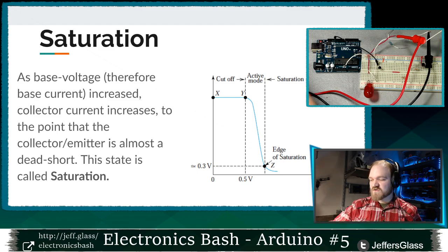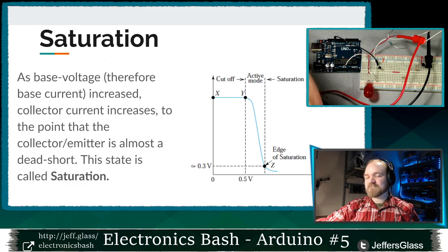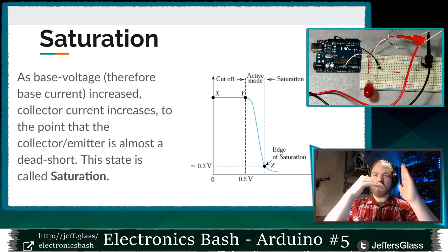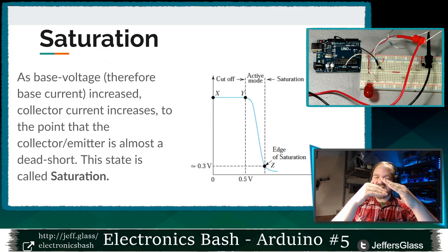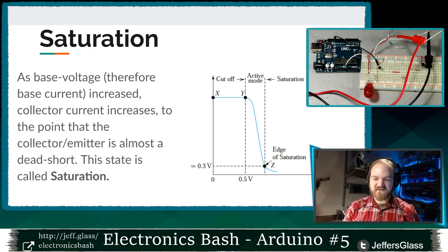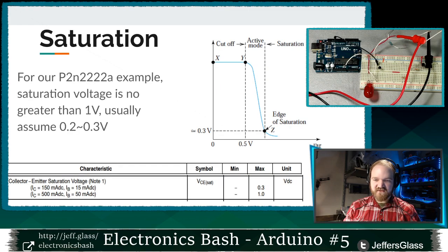And so essentially what we're doing here is making sure that we're driving our transistor into saturation every single time we use it. We want to use it as open or closed. We don't want some intermediate state where it has some intermediate resistance or something like that. We want to saturate that transistor.